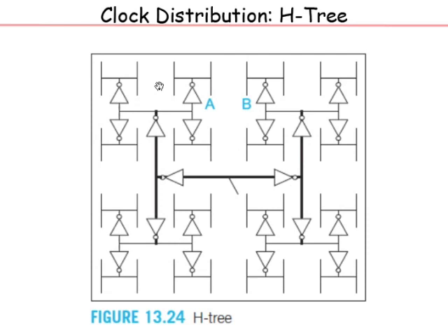So you see it's a self-similar, fractal type design, right? This is what is called an H tree, where from the center, maybe the clock source is sitting somewhere here, you inject it into your clock distribution network, clock distribution tree, whatever you want to call it, right?